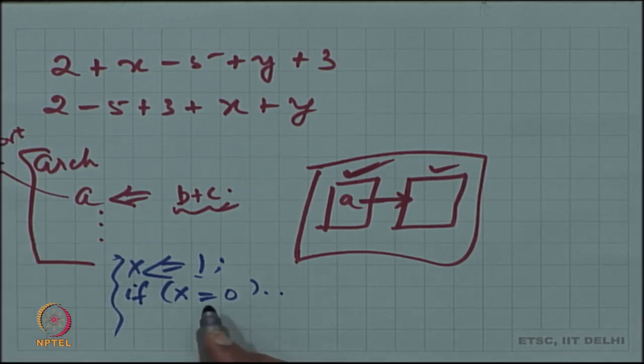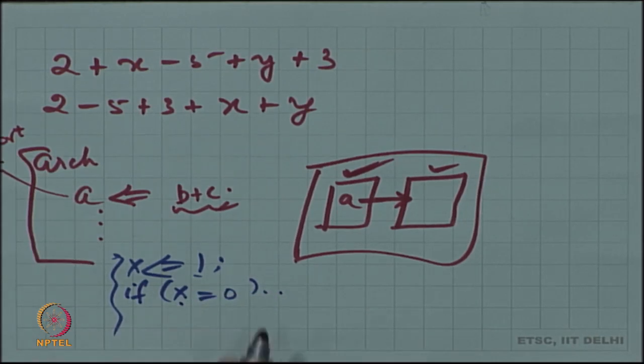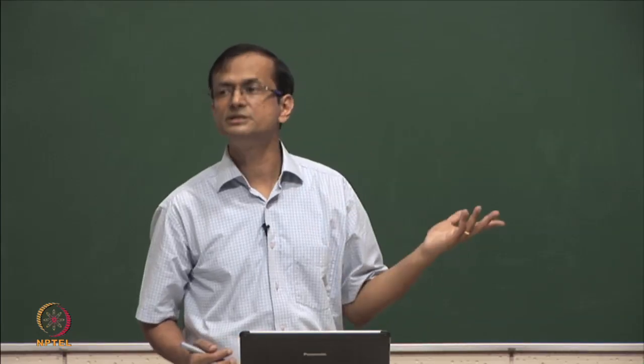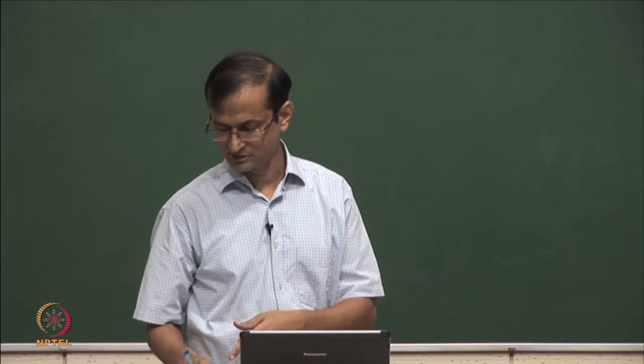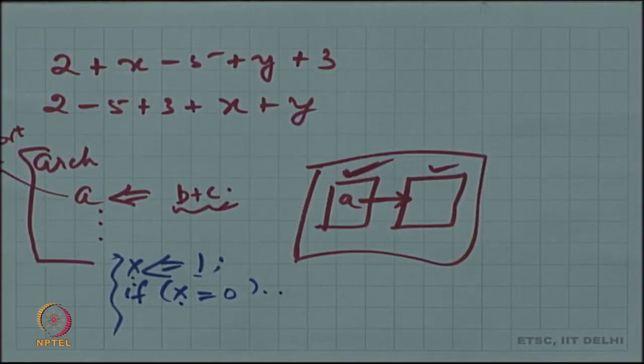Our rules are still the same, which is that this x, when we say it actually uses the old value, then the assignment is made to some other value. Remember, the way to understand signal assignments, we said, was to pretend that the assignment is happening to a temporary variable. Since it is happening to a temporary variable, it is not visible to that immediately following statement and cannot be optimized away. The constant propagation does not work.